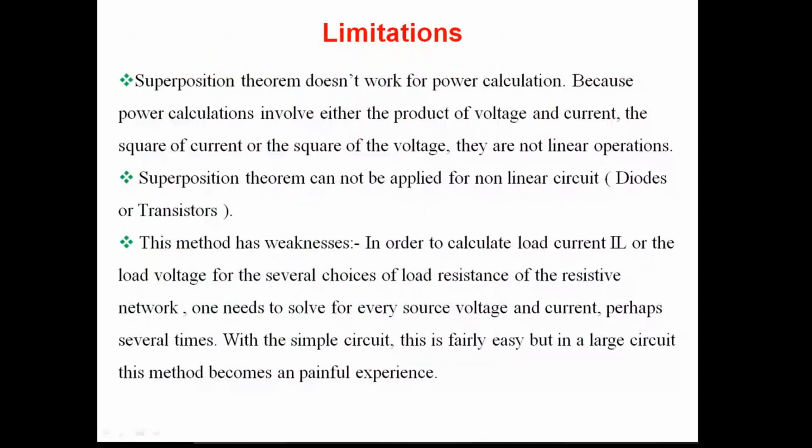Then the limitations of superposition: the superposition theorem does not work for power calculations. It is useful only to find voltages and currents in branches. But for power, we cannot use the algebraic sum of the powers, because power calculations involve the product of voltage and current, or the square of current or the square of voltage, so they are not linear operations. So the superposition theorem is not applicable to power calculation. Also, the superposition theorem cannot be applied to nonlinear circuits, such as diodes, transistors, etc.